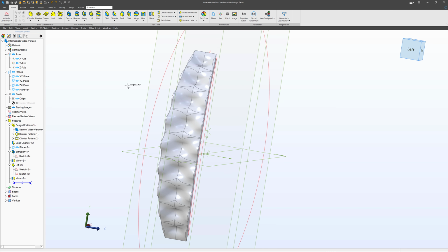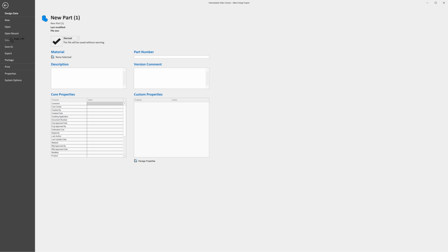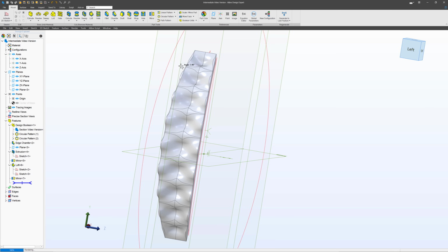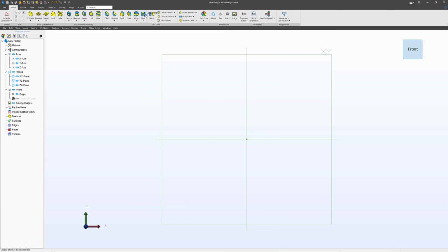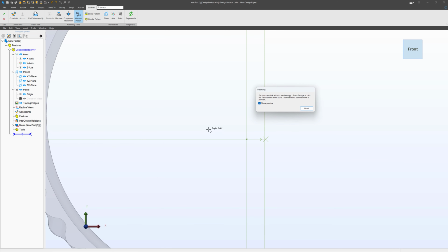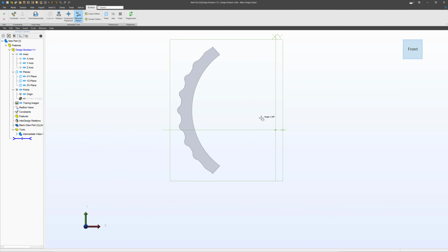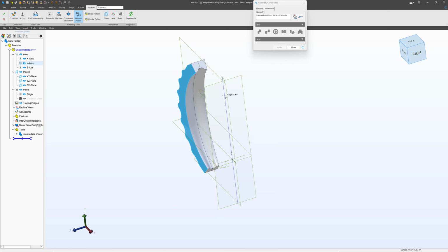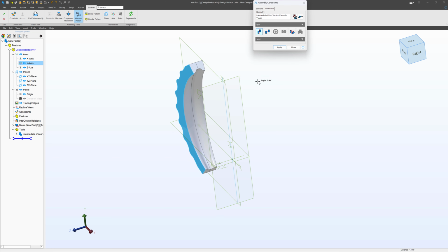And then moving right along, we'll create a new part. So here in the next modeling environment, again, we're going to say Boolean unite and insert the part that we were just working on. And I'm going to put it nowhere in particular because I do want to have the control of mating it myself. We're going to add a constraint. Of course, we know we want this face and this axis to be coplanar because that's how we pattern things properly. So we're going to apply that.